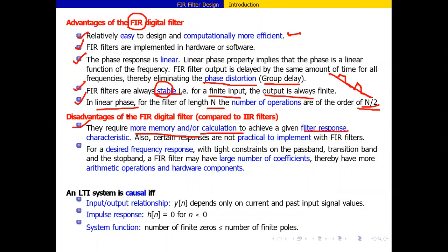But in IIR filter, if you write a single loop, that is enough. It continuously repeats the same thing for infinite times. So the memory requirement is very less. Only one loop of samples you need to store. Remaining, every time it will take from the same bank. Because of this memory requirement, it is practically not convenient to implement FIR filters if they are lengthy.